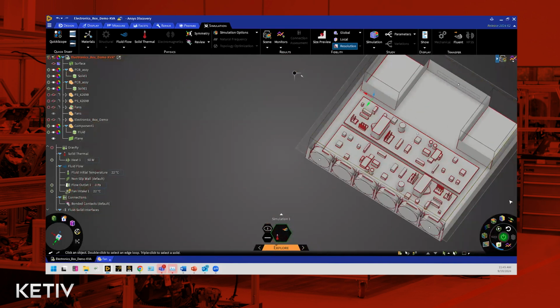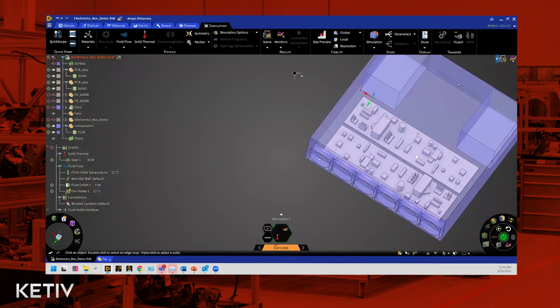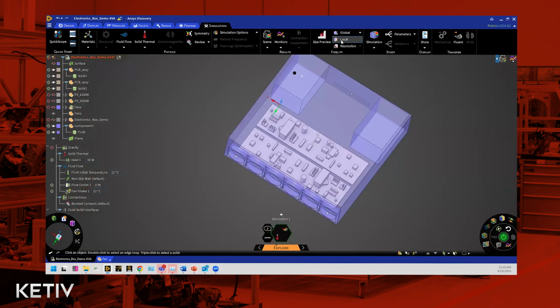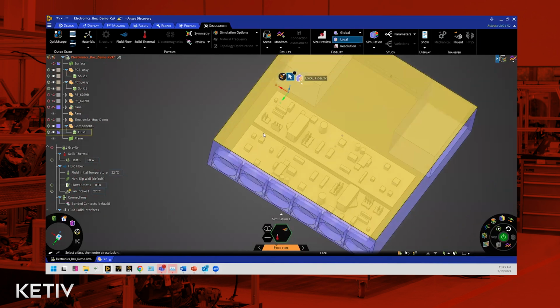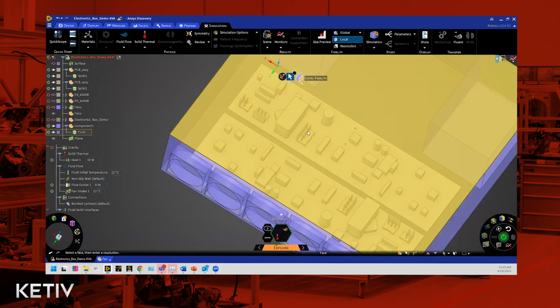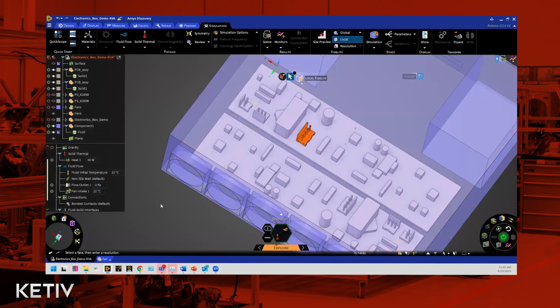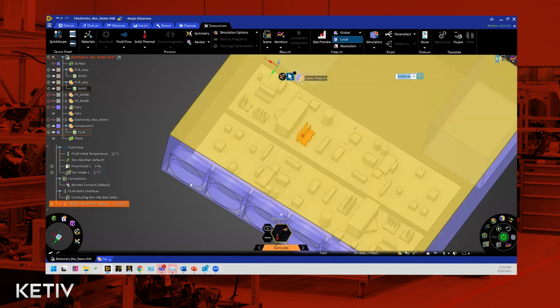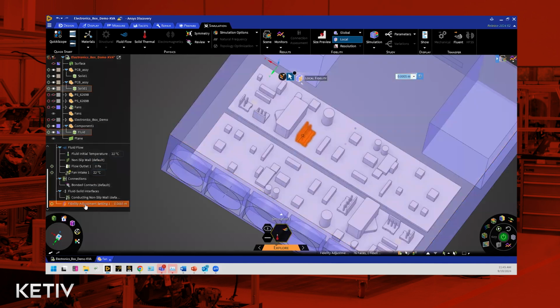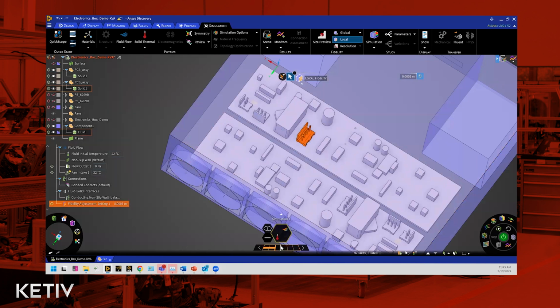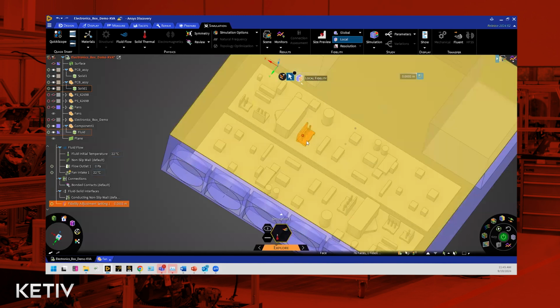So the way you do that is you can basically go ahead and add local sizing. And let me just choose this particular guy over here. I can enter a value of 0.5 millimeters. And when I do that, you will notice this particular setting being populated in your physics tree. And instead of using the global sizing of 1.48 millimeters, for these particular faces, now Discovery is going to be